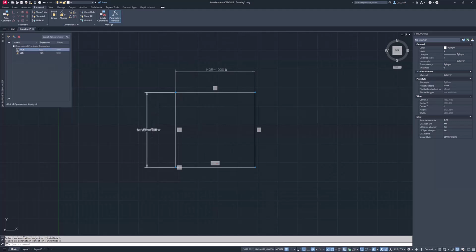And we're going to do a basic calculation in here. So we might want the horizontal to be 1000, but we want the vertical one to be half that length. So if we go vertical equals horizontal divided by 2, you'll now see, once I click out here and close that, the vertical is now half the length of the horizontal distance. So over here, horizontal, we have a real number that's been stated. Vertical is being calculated by using horizontal divided by 2.